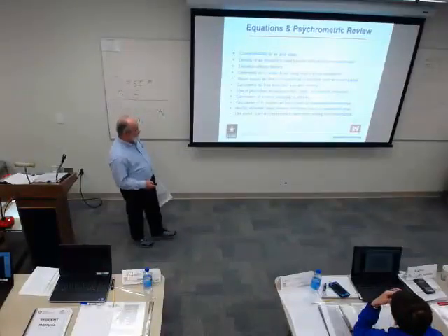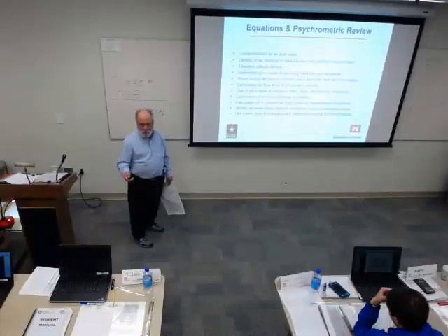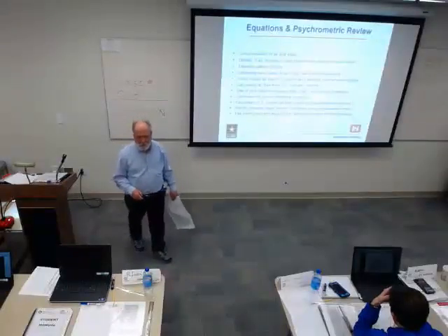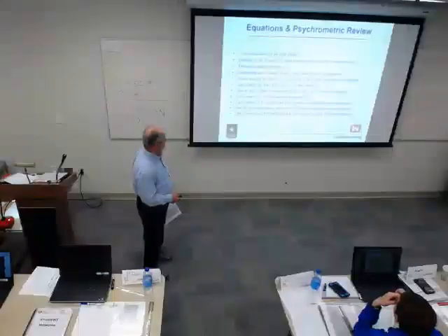Calculation of outside air for mixed air properties. What you're doing is finding mixed air properties, which are going to be the weighted average of the incoming streams. If you think of it like that, then it's pretty easy to come up with what your mixed air properties are.